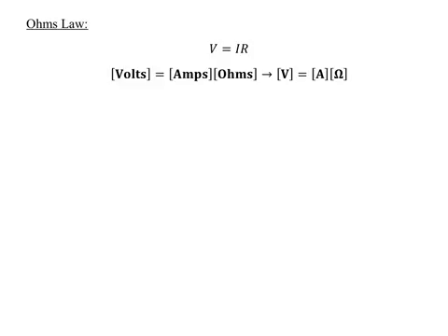All right, so now we're going to take a moment to look at what's called Ohm's law. And this is where I was talking about the term ohmic a moment ago. So Ohm's law is very similar to Hooke's law. Remember Hooke's law was F equals negative kx? Well, it was 2 things multiplied equaling something else. Same idea here. So the voltage in a circuit is directly related to the current, I, and the resistance, R. That's what those stand for if you didn't know that. We went over current yesterday, so you should know now that I is current, but R is going to be resistance. So the voltage equals the current times the resistance.